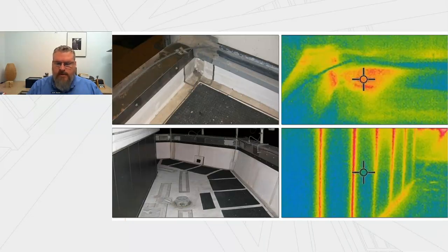The reason that we run it in both directions for this IR imaging is because you're going to get differences in surface temperature not only from air leakage, but also just from the difference in the resistance values of the assembly. So you don't always know. On this left-hand side, you've got this metal panel enclosure with these seams that are clearly warmer, same building, cold day, and we're pressurizing the building, so we're looking for warmer spots.